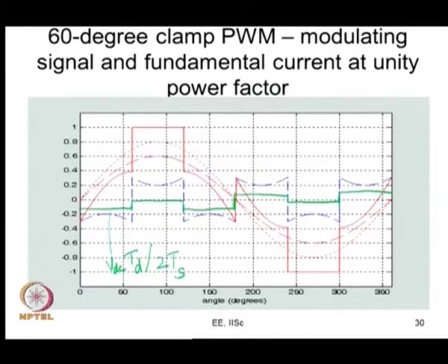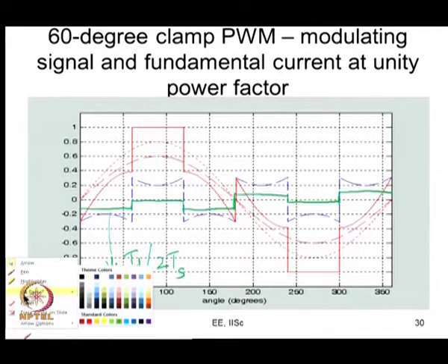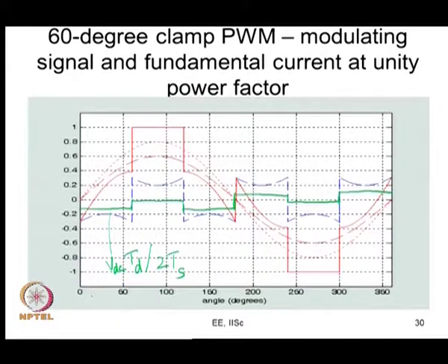So this is the nature of error voltage, and now this error voltage is getting applied. What you are going to get is not this sinusoid, but along with this modulating signal, this will be your average pole voltage, but on top of it this error voltage is also getting added. So this is what will happen now. If I do that, let me choose another color of ink. So if I subtract this error voltage, what happens? I get something like this. So here there is no error voltage.